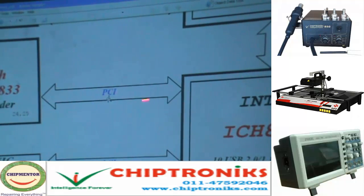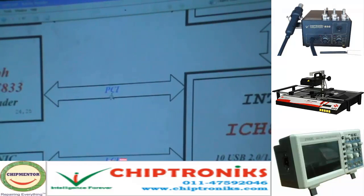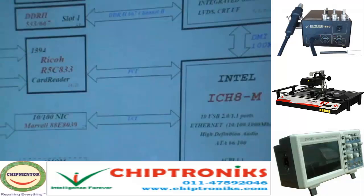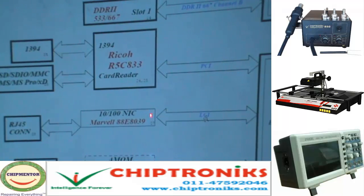This is PCI, not PCI Express. PCI Express is a point-to-point connection. This is a parallel connection. LCI is a special kind of connection between the ICH and these LAN ICs. LCI, that is LAN Connect Interface.